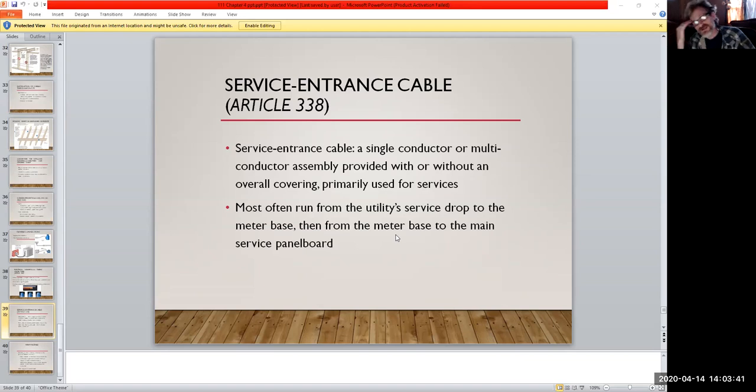So match, this is why we go through and match wiring sizes. And again, you can always go larger, but there's going to be extra cost for that stuff. So we try to match up. We do service entrance calculations and size up the wire depending on the service, right? Like I say, 100 amp, 200 amp, and so on. And we're going to match up that specific wire size and what we're going to use. And of course, how long your run is. So that also includes the voltage drop calculation. Because if you're like a gazillion miles away from your transformer, well, you're going up in wire size because of that.